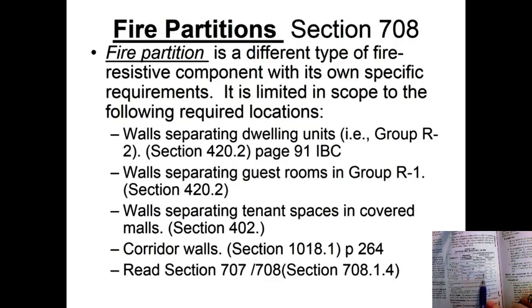A residence, okay, here we are in the hotel. Even though we have a sprinkler system, you still have to have 30 minutes, 0.5, a half an hour to be able to get out, because people are going to sleep soundly in their hotel rooms, and you want to make sure that even though you might wake up, it may take you a little while, you still have time to find that stairway to get out of the building.